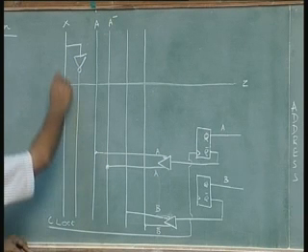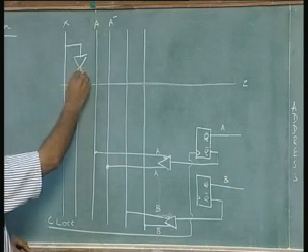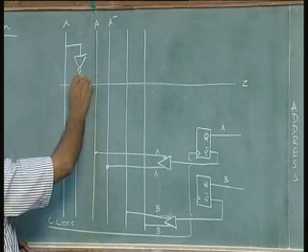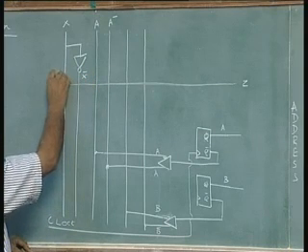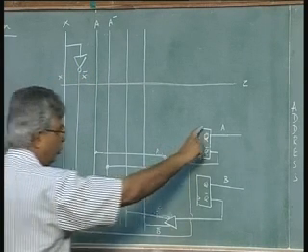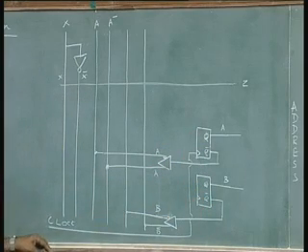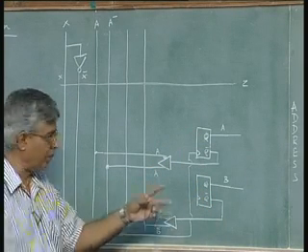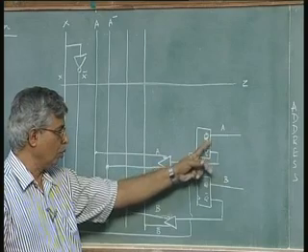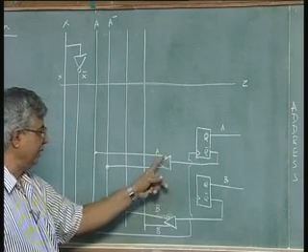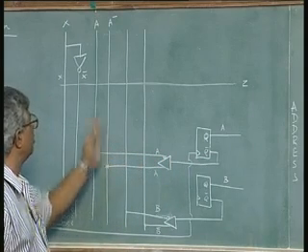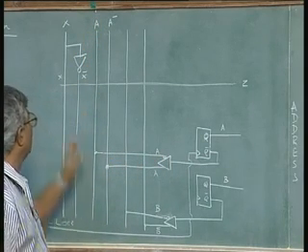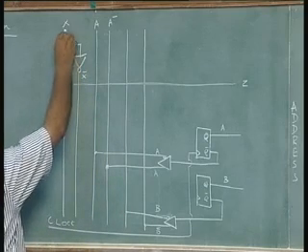So we have this X given to this, and X bar, of course. This is X bar. I have 2 flip flops. There are many registers in the output. I am going to choose 2 of them. One of them, Q and Q bar, is fed back. This becomes A bar, so I put an inverter, so A and A bar. So this also acts as an input to the combinational logic. So these are all the inputs of the combinational logic, X, A, B.